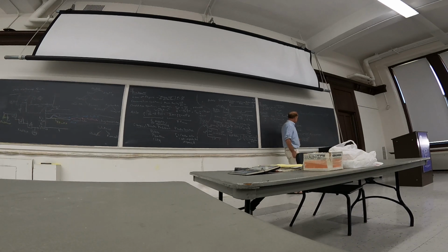So from Bernoulli's equation, we have that the velocity, and here I should use U. This is U, because I'm stating V for the volumetric flow rate. That's U. And of course, V0 would be U0 times the cross-sectional area of the pipe. So here you can see that K would be equal to A0 times root 2G.